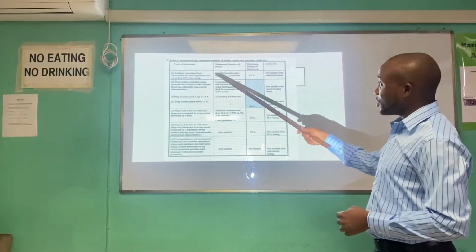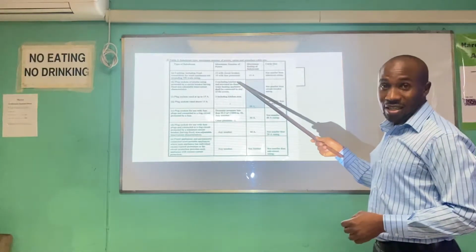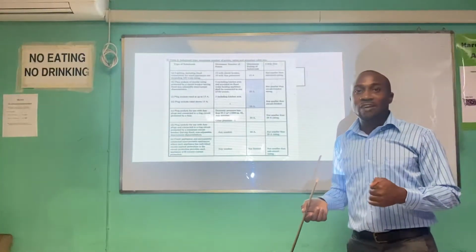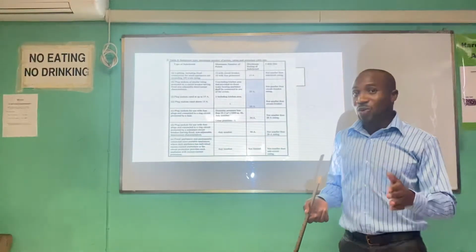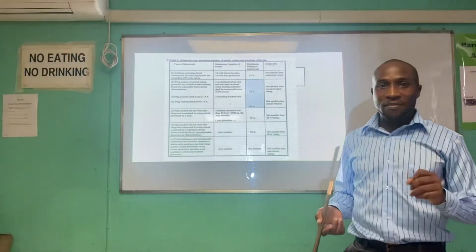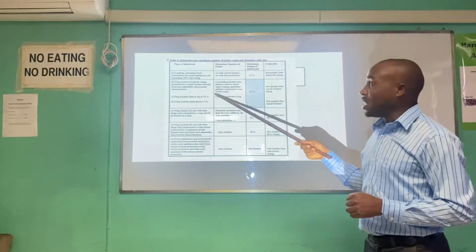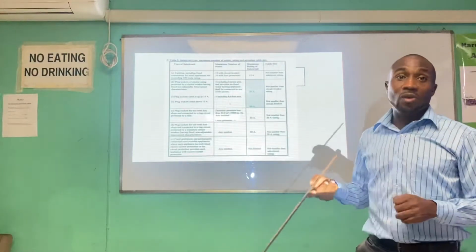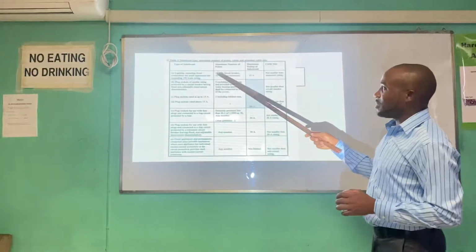Right, so 12 light fixtures per light circuit and 5 plugs per plug circuit. So if you have 20 plugs in your house, excluding the kitchen area, that is telling me that you need a minimum of 20 divided by 5, which is 4. You need a minimum of 4 20 amp circuits for plugs alone. Following?